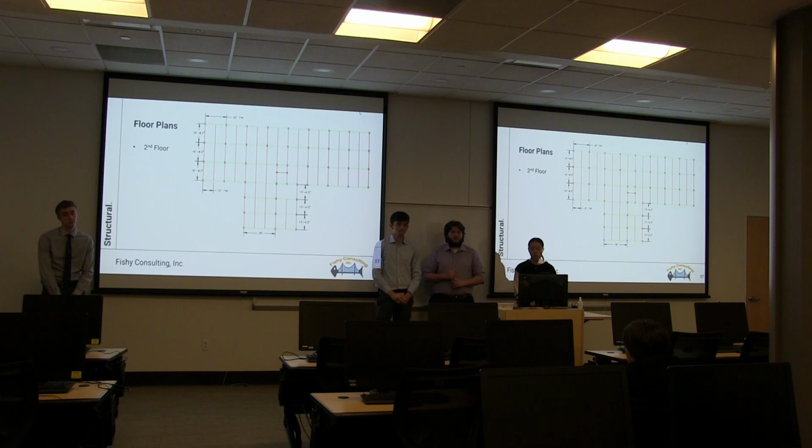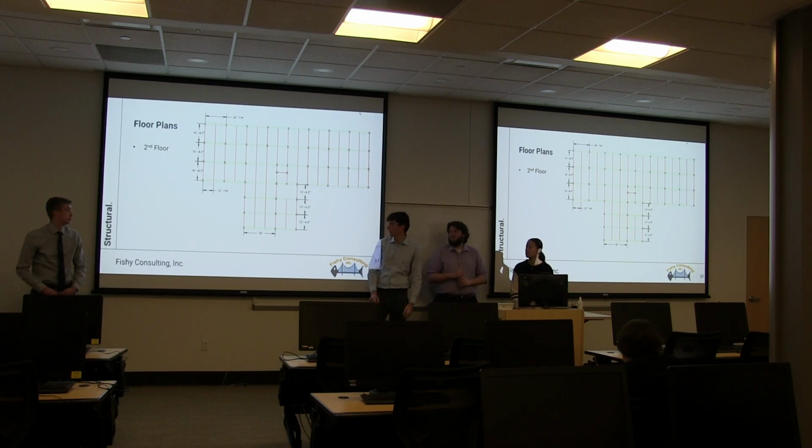You also mentioned, and we have talked about it, so I'm not going to ask too many questions about the lateral load resisting system, that it's a possibility that you use masonry shear walls. With the size of your structure, do you think you should use a reinforced concrete shear wall or a masonry shear wall? Either is a possibility.